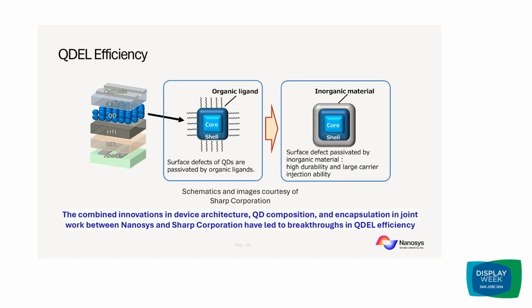Blue quantum dots have always been the area of the greatest concern. And this is something true of all electroluminescent materials. This is not unique to quantum dots. It's true for the organics also. The simple fact of the matter is that for blue quantum dots, your band gap is the widest compared to green and to red, which means that in the excited state, first of all, you have a very high energy level of the charge that you're injecting, which means that it is more possible, and there are many other choices, for it to transfer to other acceptors in the system. So basically, just the nature of where that energy level is creates the challenge in the system.